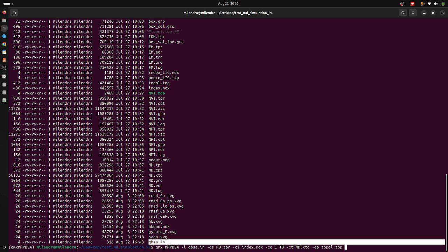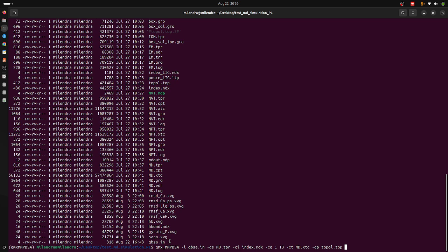This file contains the information about the parameters, like how many frames we are considering for the calculation, right? What is the method, GBSA or PBSA? What other calculations we want to consider, like per residue decomposition, or binding affinity, and all the major calculations we need. So I have put all the parameters in this gbsa.in file, right?